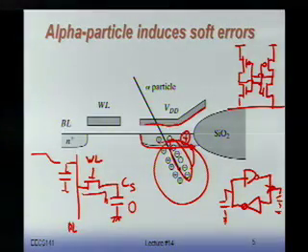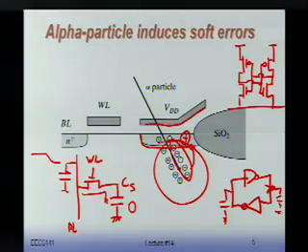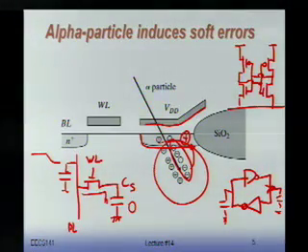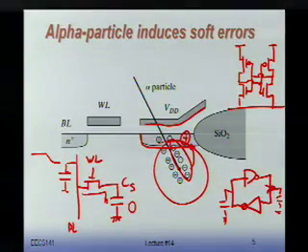And you will see that if you go to the most advanced memory chips today, people start adding error correction on it. So error correction is something which we didn't used to do. We only used to do it for DRAMs. We definitely do it for non-volatiles. Every flash memory has error correction on it because the more you read and write it, you get some degradation. So if you want to increase the number of read and write cycles in a flash memory, you use error correction. But SRAMs is really the newest thing.